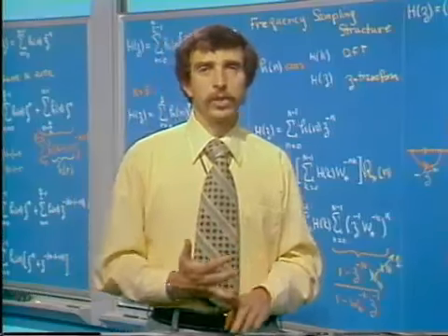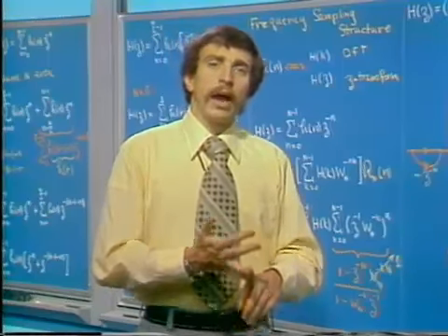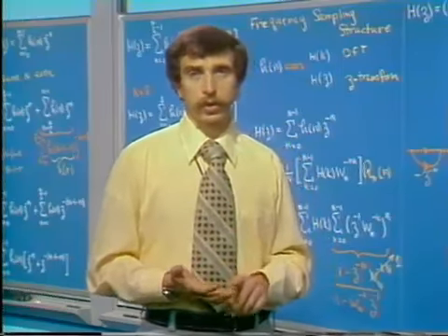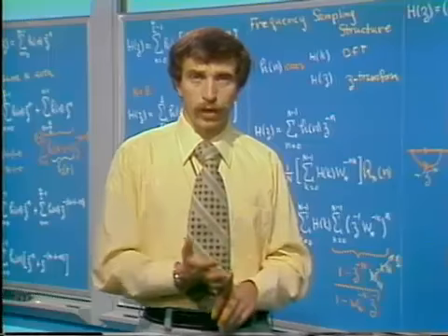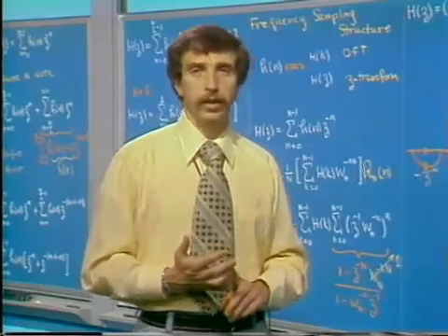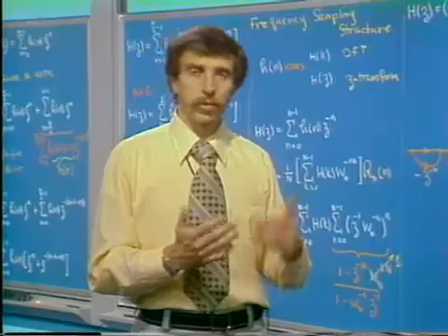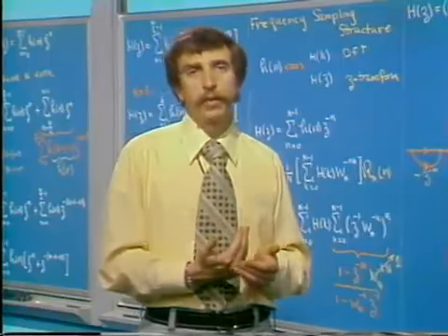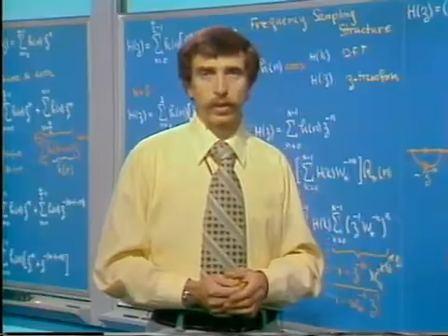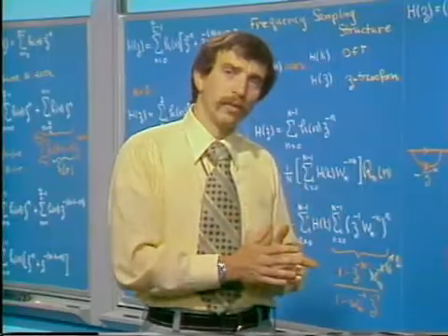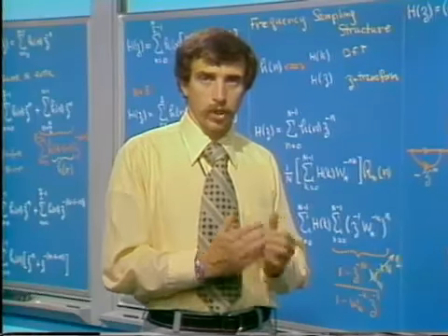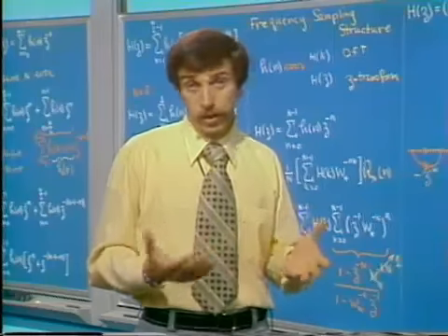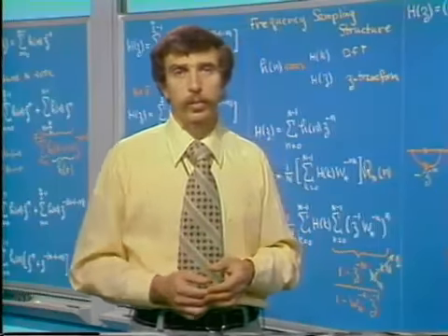One of them has to do with the fact that arithmetic in a digital filter, specifically in a recursive digital filter, has to be done, of course, with finite register length, and it has to be truncated. In other words, multiplications, the result of b bits times b bits results in 2b bits. If this goes on indefinitely, obviously the register length grows indefinitely. And so the results of arithmetic have to be truncated or rounded. And this generates some noise, essentially noise, in the filter output.